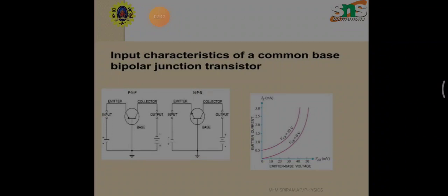So we know that in the transistor a large collector current corresponds to a very small base current. Therefore, for the input signal applied to the base, a very small change in the base current produces a much larger change in the collector current. This way a very substantial current gain is obtained.